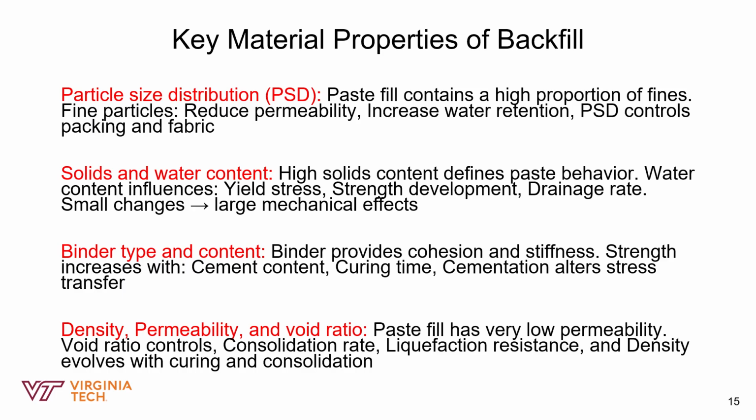In backfill, the majority of the expenditure goes into cement, so determining the right amount of cement to use for a backfill application is very critical. The fact that more cement means more strength doesn't mean you go with the highest binder available. No, because you need to optimize some parameters, and the binder content is one of them.